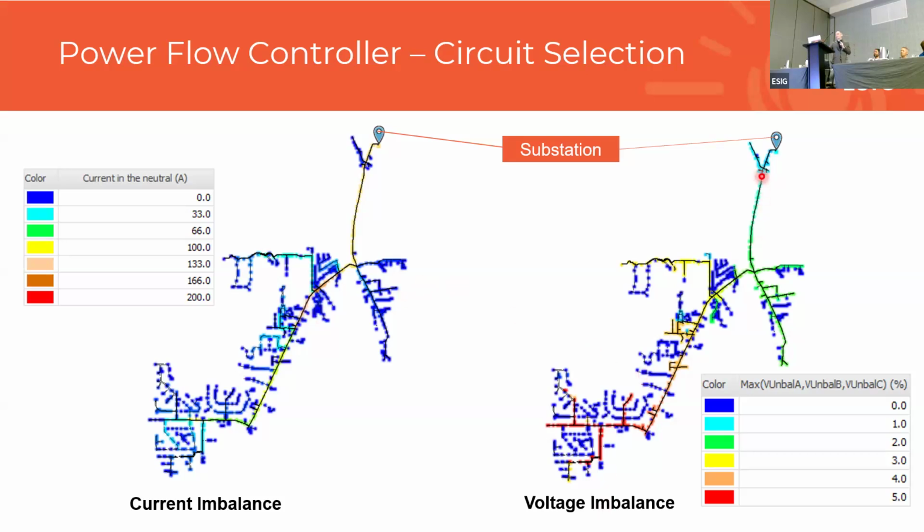Thank you. You can see that voltage imbalance accumulates as you move down the feeder. And that makes a lot of sense based on what we were just talking about. You're dragging unbalanced current flow through impedance. Your voltages are just spreading out and fanning apart. So near the end of the feeder, you've accumulated quite a lot of voltage imbalance.